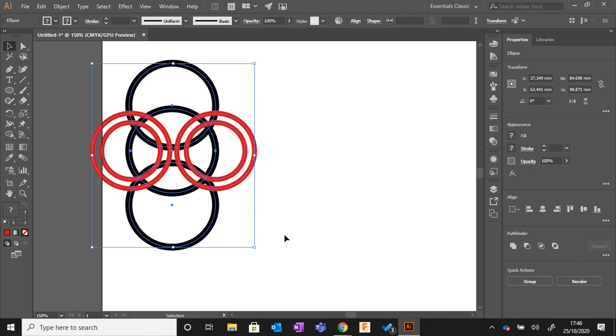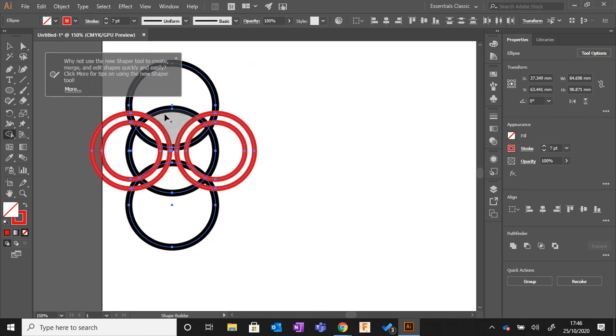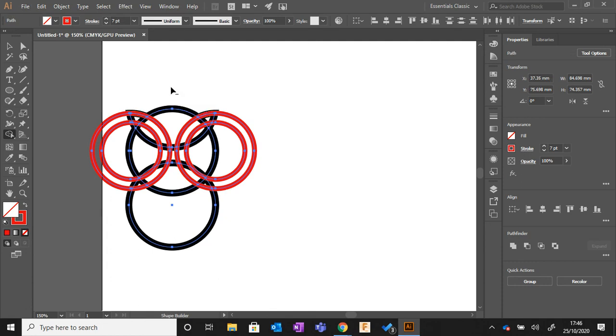And if I want to do something a bit more creative, Adobe's got this real cool tool called Shape Builder, which is here. So it's in the tools. If you click that, what you can do is when you hover over things, if you press Alt or Command, the plus turns to minus, you can click it and it chops pieces out. So if I undo that, you can see that this grey area is highlighted, and it chops that bit out for me. Okay, so I'll show that again.